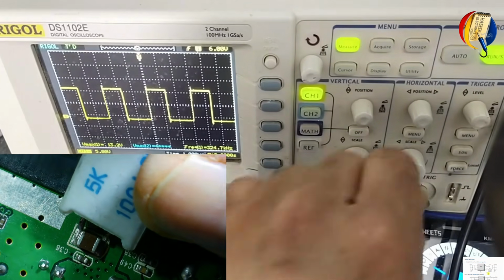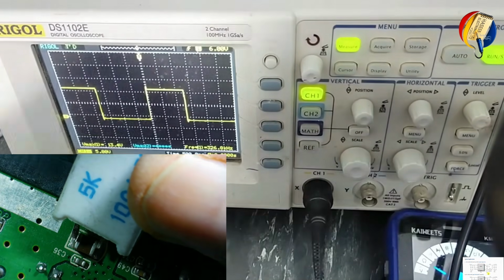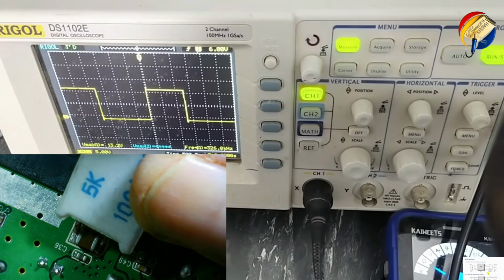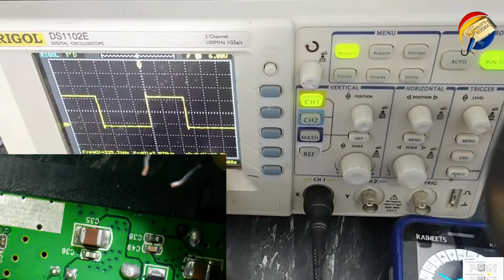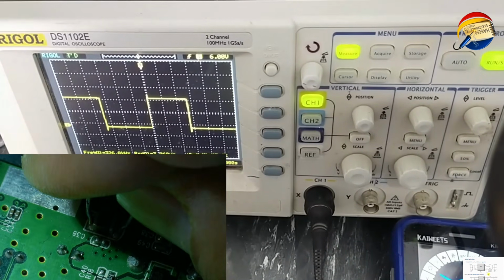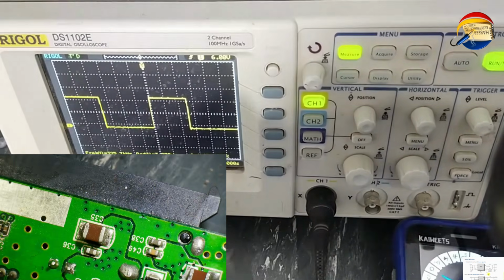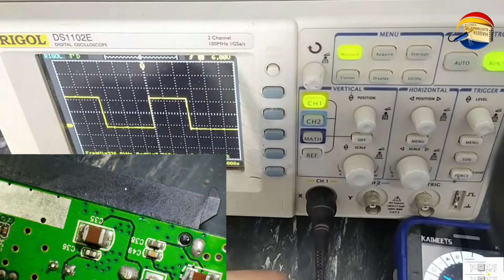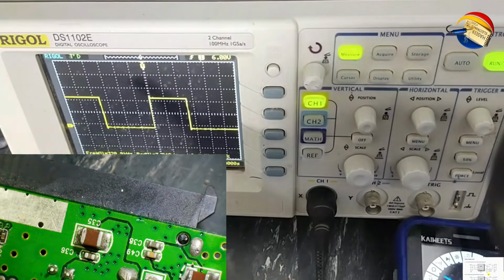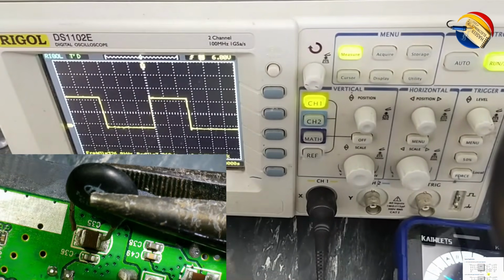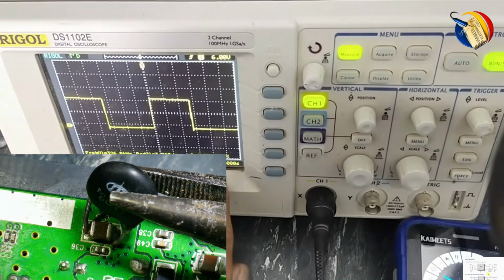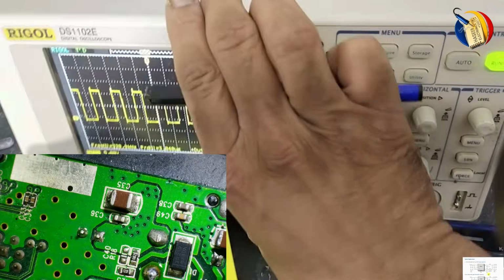If I connect a load, when I am connecting the load, it is changing its duty cycle. This time, no load, 42% duty cycle, 44%, 45%. I am connecting this NTC so that the load will increase. When it heats up, its resistance will decrease, so it will draw more and more current, and now we will see the response. 45%. How it is dropping the voltage.